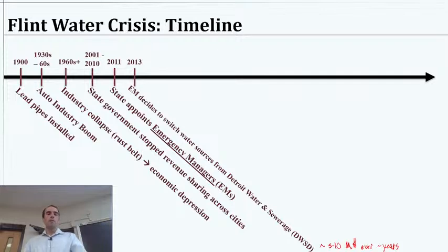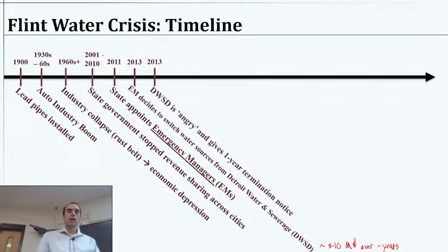So the city of Flint had a small water treatment plant, and what they'd use it for typically was to touch up the water sent from Detroit. So Detroit would take in the water, treat it, send it up the pipe, and so Flint was typically then just recharging a little extra chlorine and sending it along through their system. So that was the typical practice there. But you know, the emergency manager made that decision.